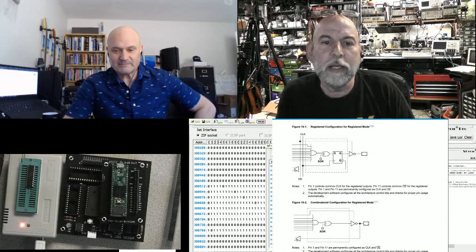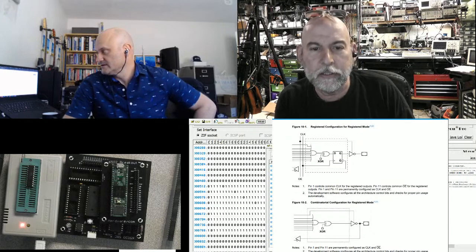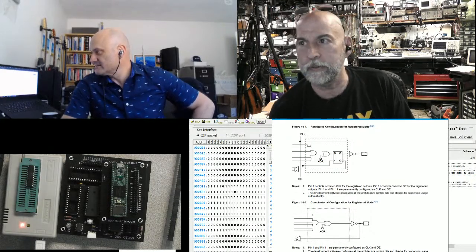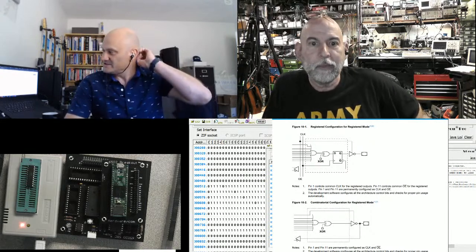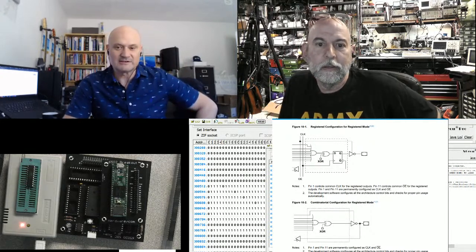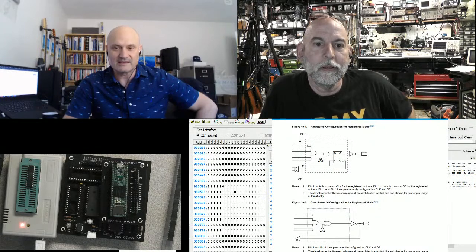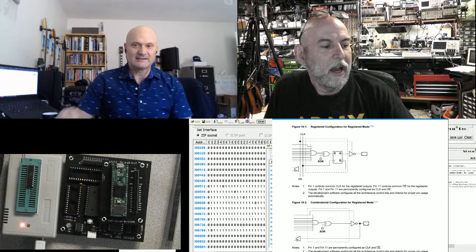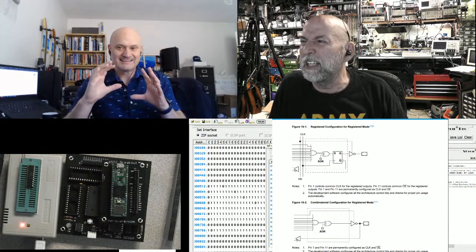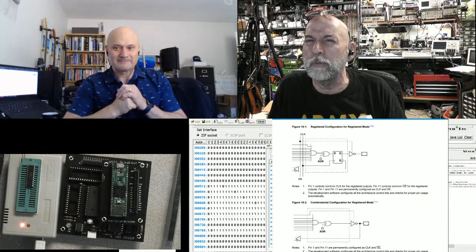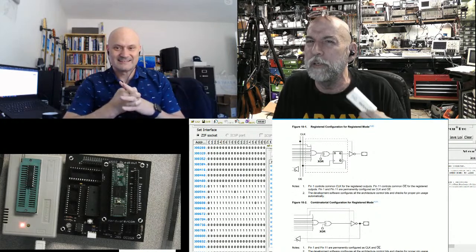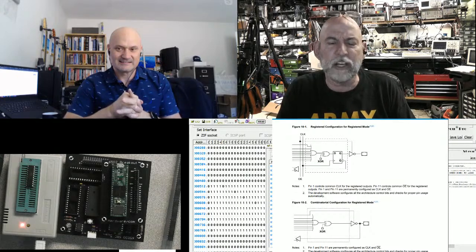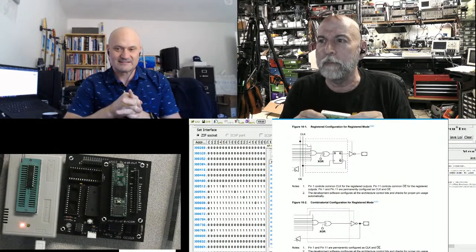So Frank just replied that the Max 10, which is correct, it's a Max 10, has 8,000 logic elements. So they're calling that an FPGA now. Maybe the Altera Max family got so big they switched over under the hood. You never really know. I call it a CPLD though. My memory about the Max family is that it doesn't need flash, and you can burn these.